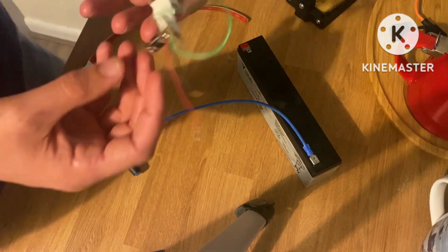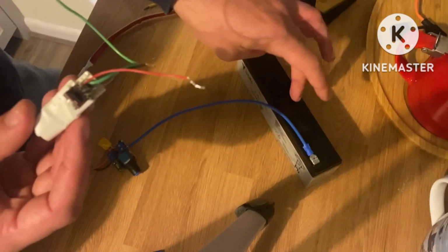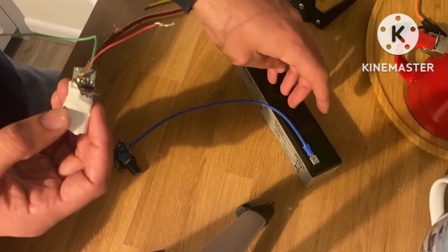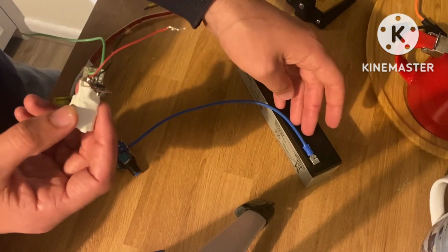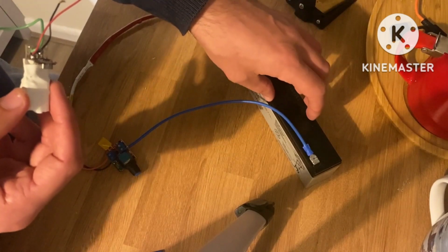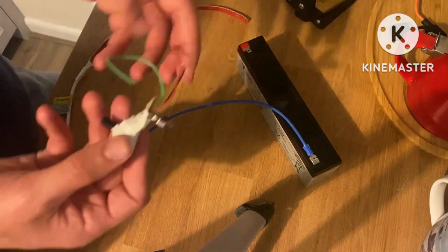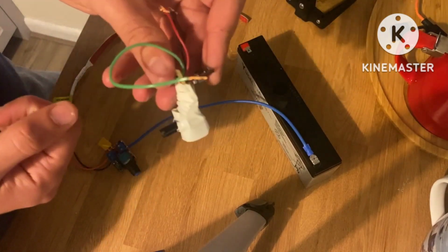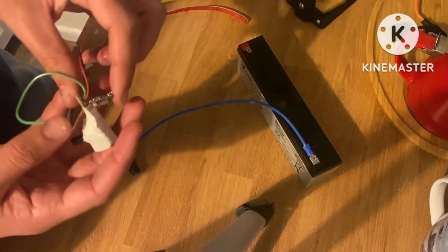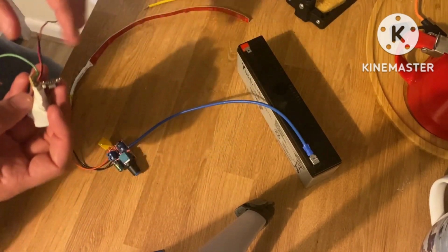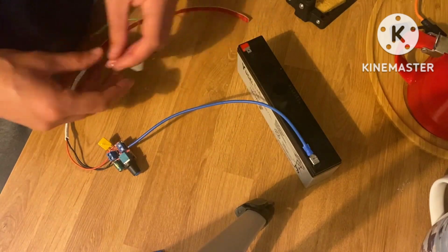But what's good about this is that almost irrespective of what the battery gives us, if it's fully charged and giving us 13 volts, or if it's almost empty and only giving us 11.5 volts, this will always kick out the same voltage, which just stabilizes the power going to your LEDs, which is always a good thing.